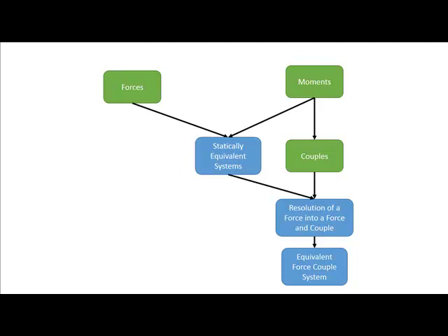With the equivalent force couple system, I take all these different forces that are acting at all these different locations, all these moments, and I'm going to move them all, using the resolution of a force into a force and a couple, to a single point. Once I have everything acting at a single point, I can sum them up to find a single force and a single couple, a pure moment, that is going to be equivalent to a much larger and more complex system.